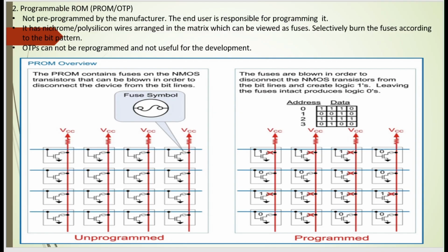Next, we'll be discussing about PROM. PROM is called as programmable read-only memory. It is not pre-programmed by the manufacturer. The end user is allowed to program, but only one time. OTP cannot be reprogrammed and not useful for the development.